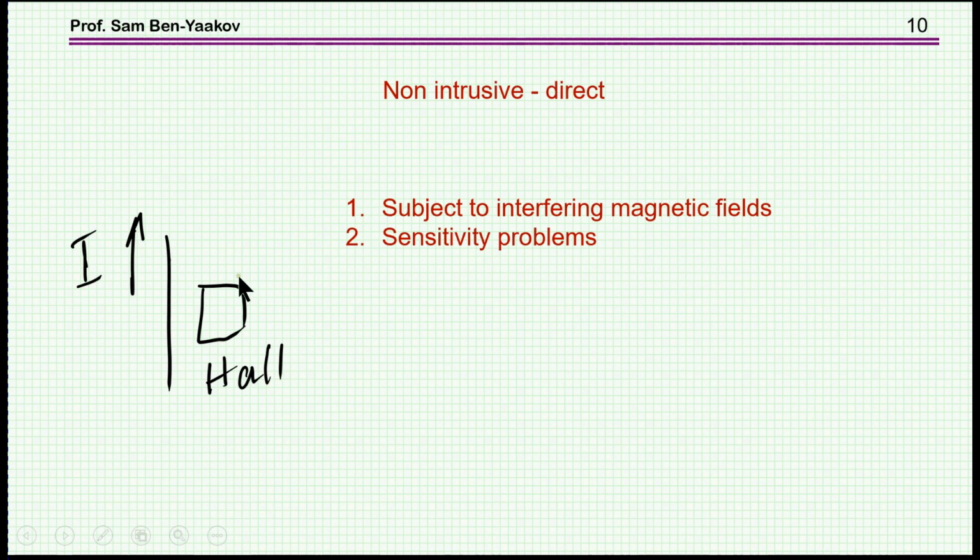In this case, we have a Hall effect element which is nearby a conductor. Now, as I've said, there are problems of interference from around the element. If it is a switch mode converter, we might have switching element, and transformer, inductors, all with magnetic field around them, and this of course will interfere here.